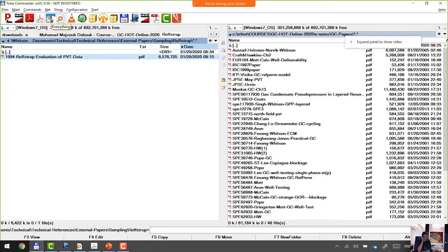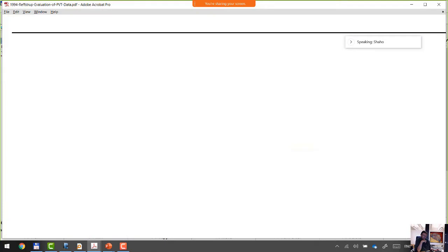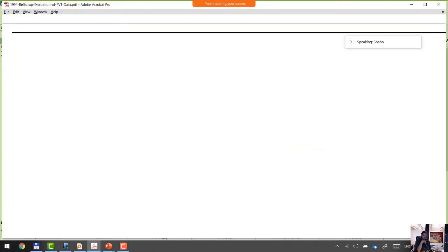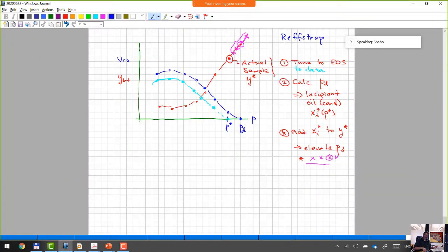Just another question. This first dropout, what I've experienced in some of the samples, it's very heavy, and it even creates anomalies in the black oil PVT table. It's not monotonic. So is it really the correct composition? Yeah, I mean, you don't really have it. It's if this composition is the equilibrium gas currently. Of course, the problem is that there are many ways to tune the equation of state.